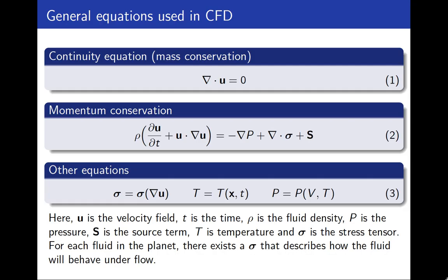If you watched my previous videos, or if this is the first time that you are watching my videos, I describe the equations that are commonly used to simulate the flow of a fluid. So we actually have a system of partial differential equations. The first one is a continuity equation, which is just the mass conservation, which tells us that the mass that enters the control volume is the mass that exits the control volume. And then in this second block, we have the momentum conservation equation, which is just basically Newton's second law.